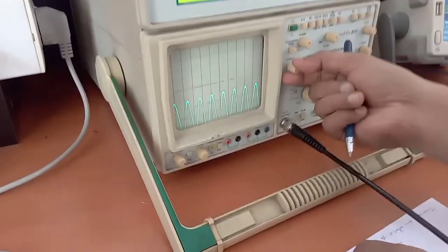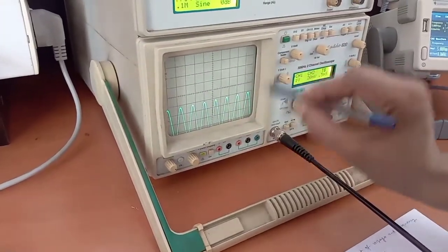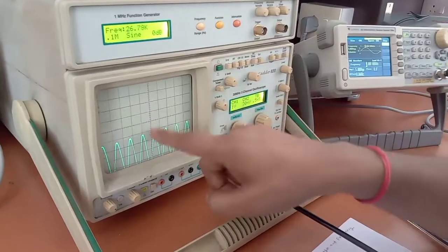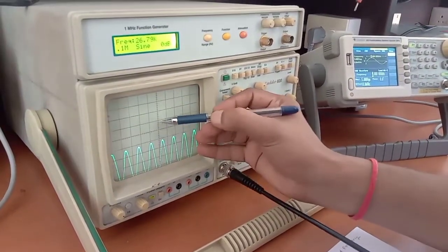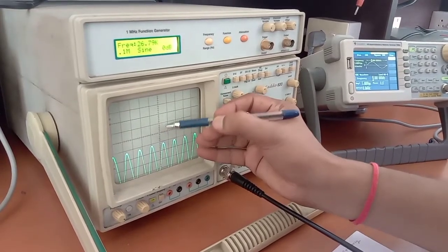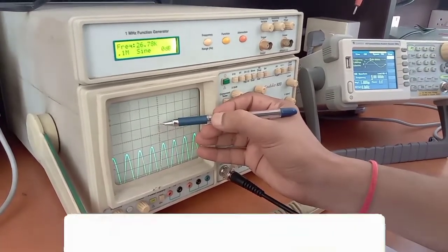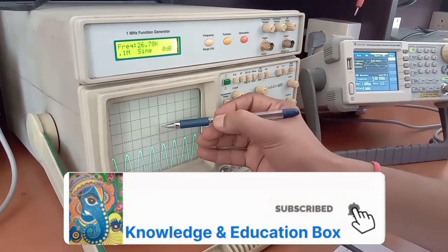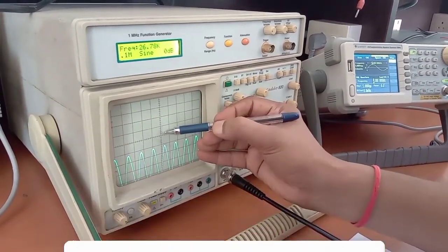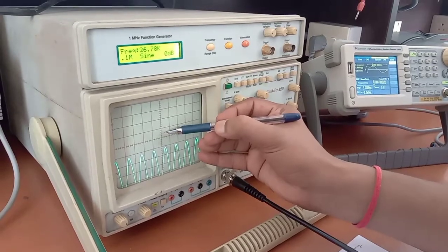If we look at it, this display is divided into two parts. This is the vertical division, and this is the horizontal division. One big division is further subdivided into 5 parts. So the subdivisions show 0.2, 0.4, 0.6, 0.8 and 1. So this is one total division, and each subdivision is 0.2 division.